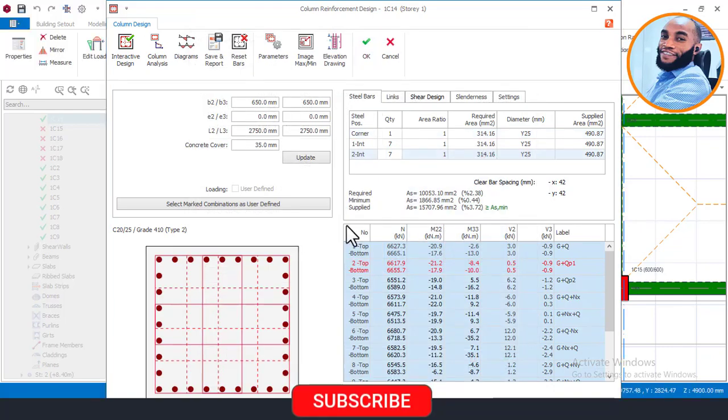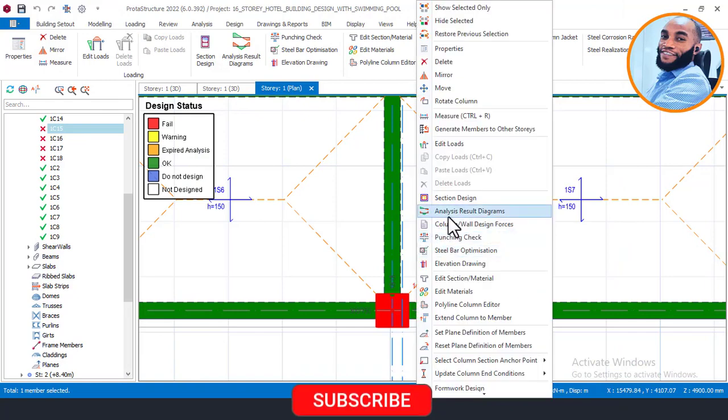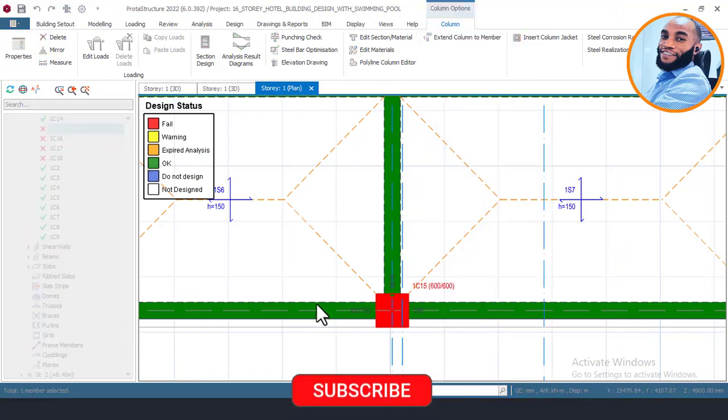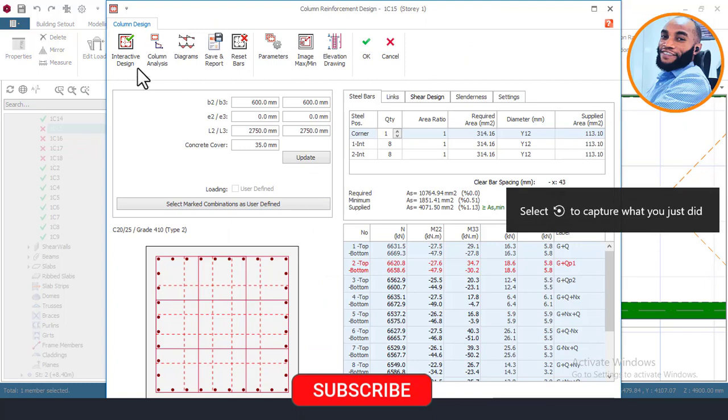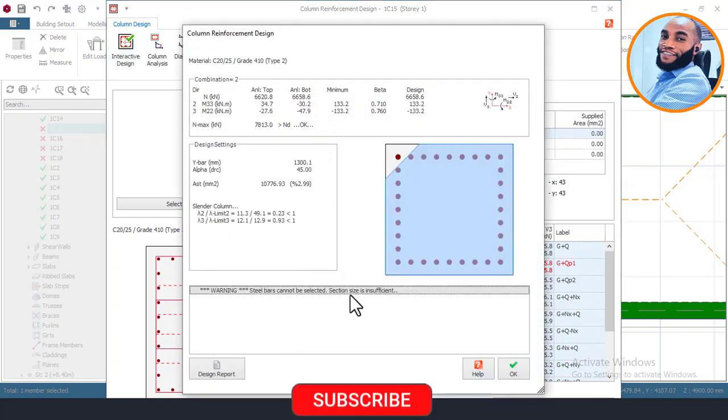That's fine. Okay, and I'll come again here and then right click here and then click on design here, and then come again here and click. Let me check again why it's failing. That should be on the size too. Yeah, the size. You can see here right now section size is insufficient. Come here and then increase.